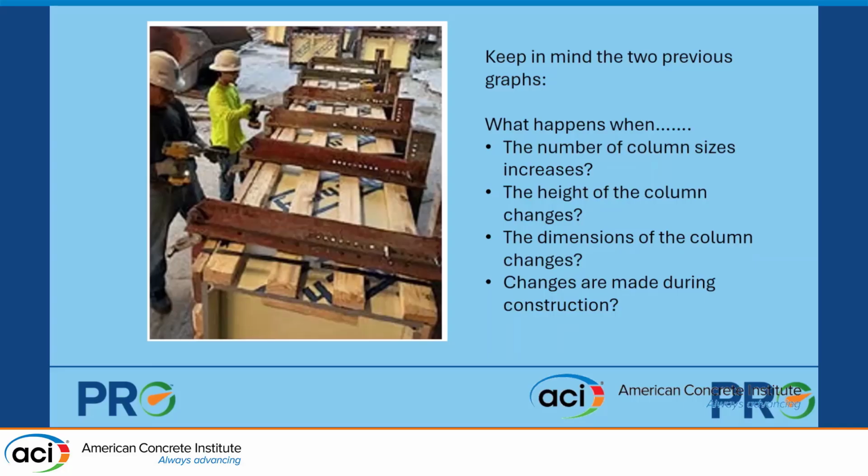Now, think about in the field with that carpenter that has to set that column form. He's got a 36 by 36 inch form on the outside, but inside that form, he's got a 30 by 36. What is the probability of error that he orientates setting that column form 90% off what it should be? So it just, and the side effects of the constructability problem associated with that. Just an illustration of how important it is to maintain some of those member sizes.